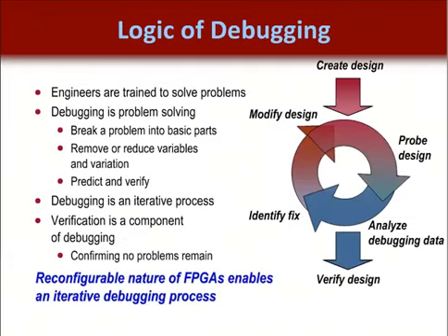Electronic debugging involves probing a design to determine what is happening on the chip at the die level. To do this, the ChipScope cores are placed inside the FPGA and connected to the nodes the user wants to test and verify. This enables a user to test portions of a design independently, then verify the design's functionality in an iterative fashion so the user can break the design down into several major components, test the various inputs and output signals of each component, and finally decide about making any design changes.